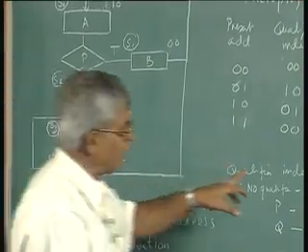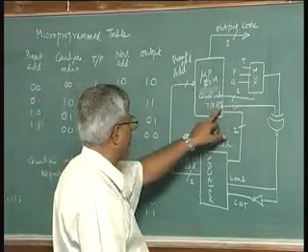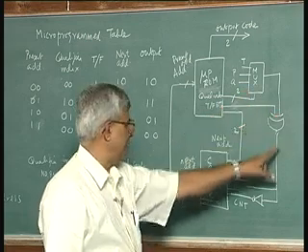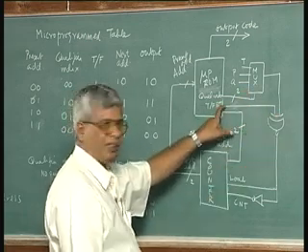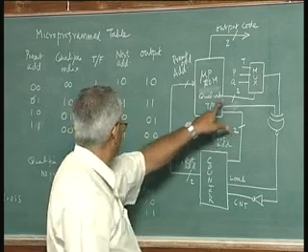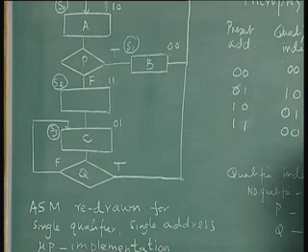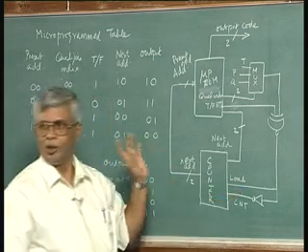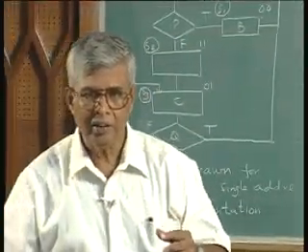So, if the true false bit is 0, this will be a 0 and this is a 0, 0 0 equal, I load it. On the other hand, if the true false bit is 1, this is 0 always. If Q is 1 and this is 0, this will increment and it will count. So, it will increment by 1 or it will load a new value.